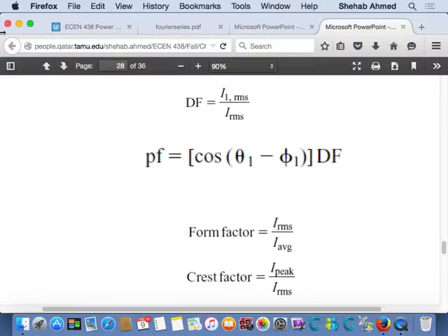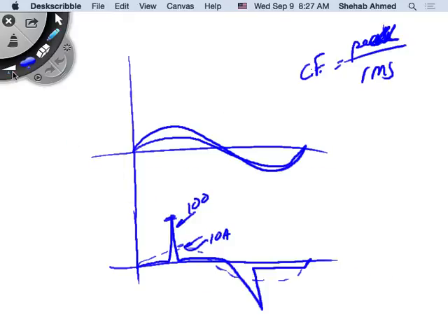Yes, sir. So the second waveform, is it safe to say that the frequency components are way different as compared to the original? Yeah, of course. I mean, this would be just a pure sinusoid fundamental wave. This will have a good amount of component at the same frequency as the sinusoid, at 50 hertz, for example, and it will have lots of other components because of these abrupt changes.